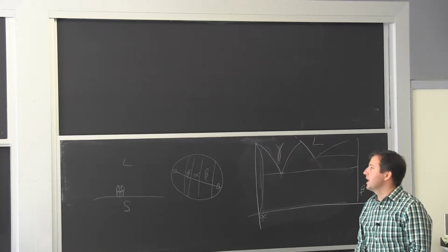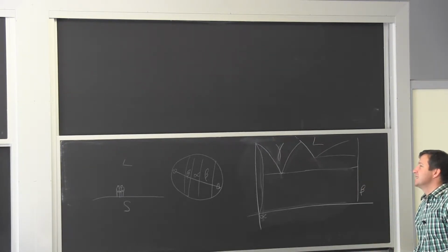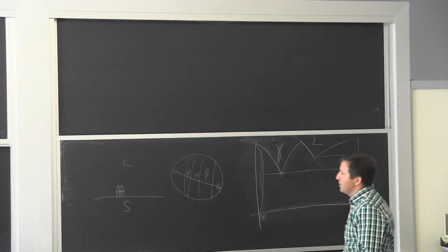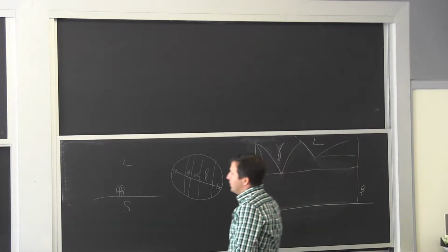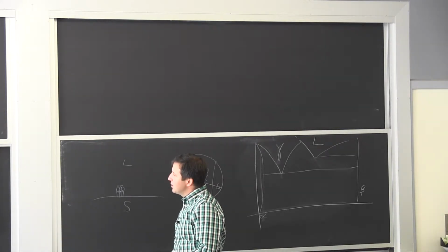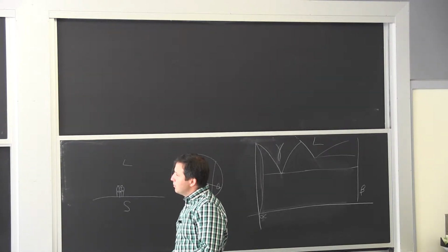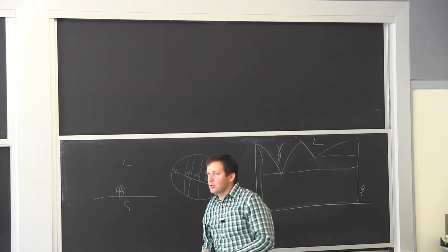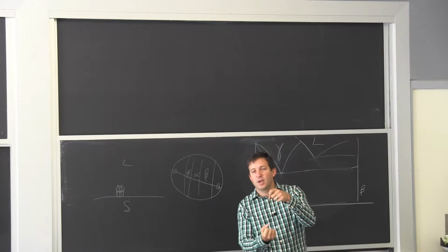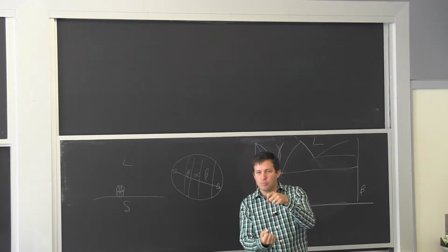So hot working has certain characteristics here. We talk about temperatures above 0.6 of the temperature of melting. If you know anything about metals or materials in general, they will start to creep. They will start to deform under just a dead load above 0.5 of the absolute melting point.